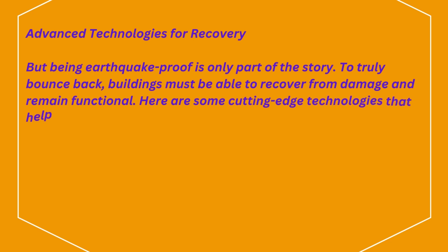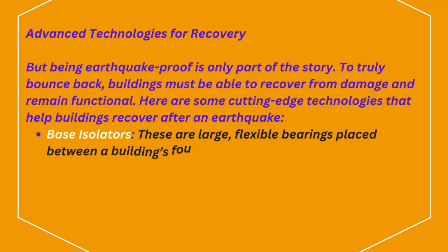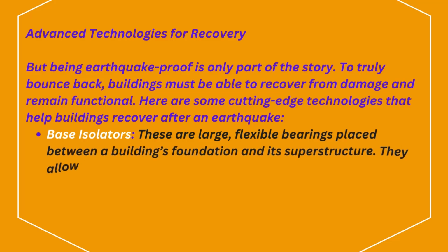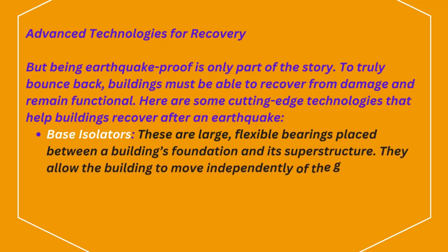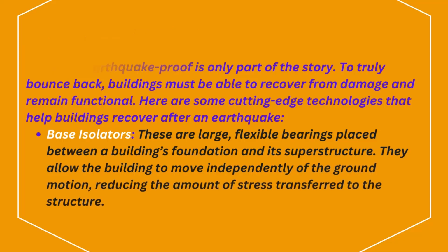Here are some cutting-edge technologies that help buildings recover after an earthquake. 1. Base isolators. These are large, flexible bearings placed between a building's foundation and its superstructure. They allow the building to move independently of the ground motion, reducing the amount of stress transferred to the structure.